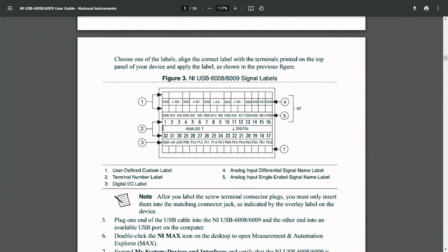Here if you see, pin number 1 is a ground, and 2 and 3 are analog inputs. As I told you, this particular device can support 8 single-ended channels. It can convert the input voltage using a 12-bit ADC. If you are using single-ended information, such as the resistive divided output voltage we have discussed previously, we can utilize all 8 channels.